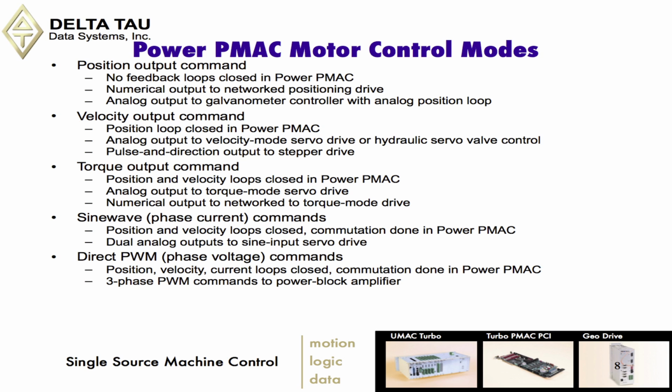And that's almost always determined by the type of drive. So on a typical velocity mode drive, there has to be a feedback device going to the drive so it knows what speed the motor is going at, so it knows how to take care of its own internal current loop.